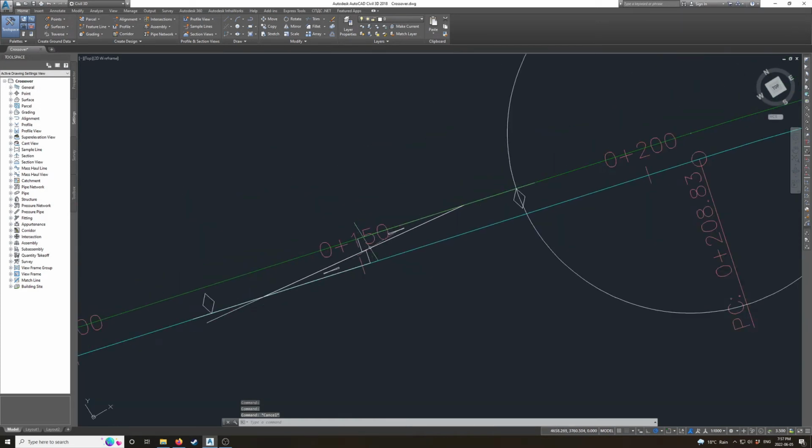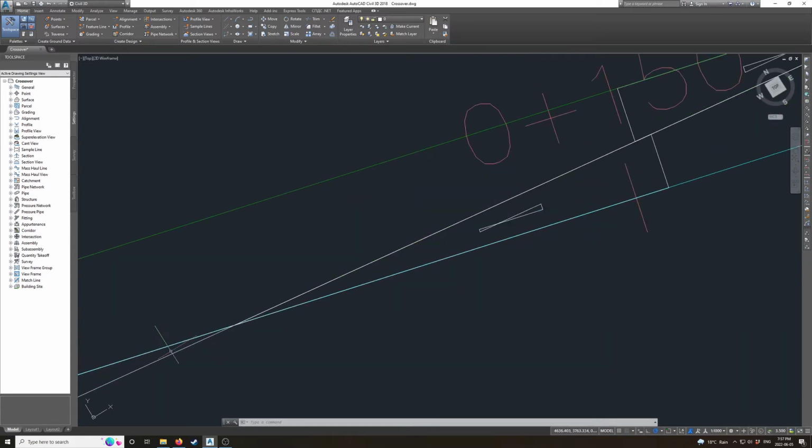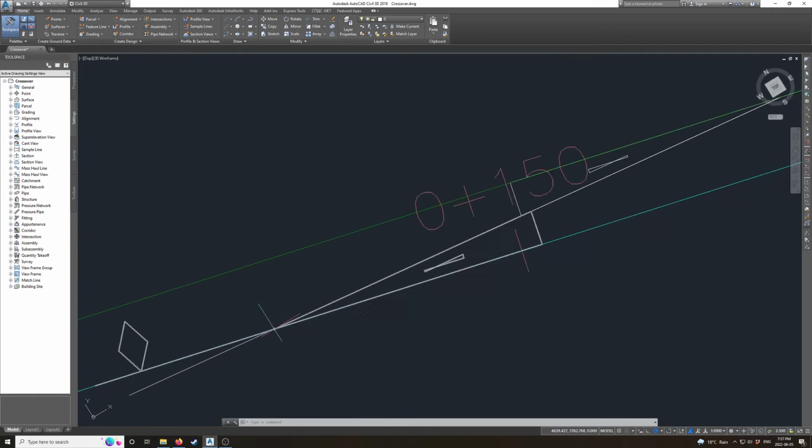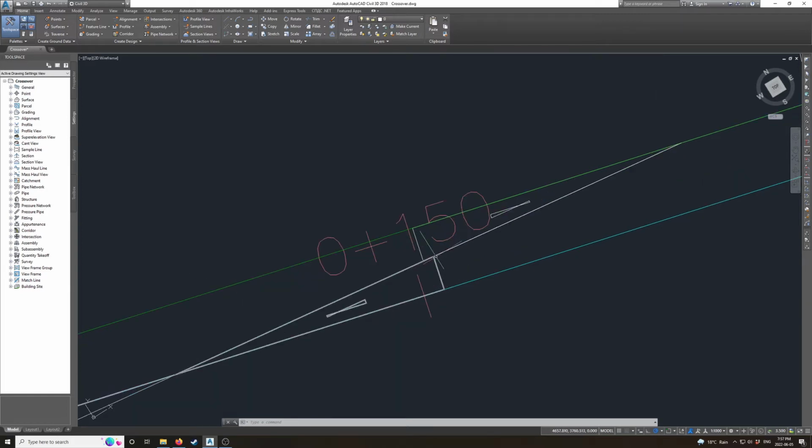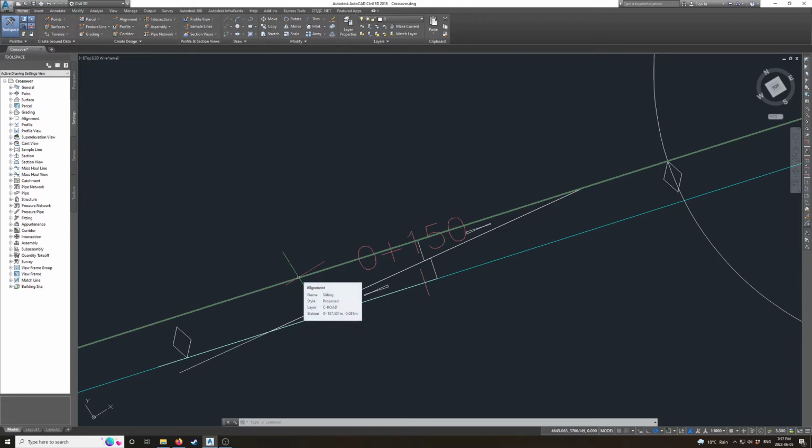One thing you'll need to ensure is that the two tracks are parallel, and since we did an offset, they should be parallel. And make sure that you pick the PI of your turnout where the bearing of your turnout meets the other track. The overlap between the long ties is just a function of your track center. Since I used a 15-foot track center, there's just a little bit of overlap. If I use a 14-foot track center, there will be more of an overlap, and vice versa.